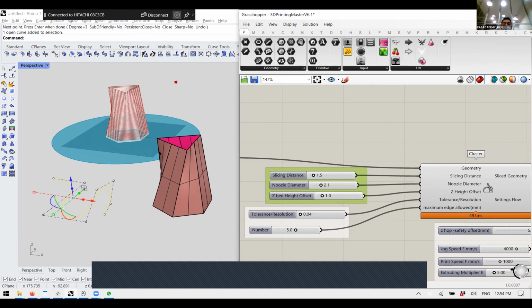So how do we control the machine? We use Repetier, which is a software that allows us to directly control the machine. So with these machines, we don't print with an SD card, we connect with a USB. As you see right now, I have the other printer. I change the program to choose the other printer: config, printer settings, printer. Okay, I connect the machine,